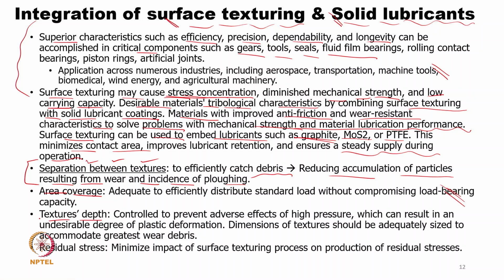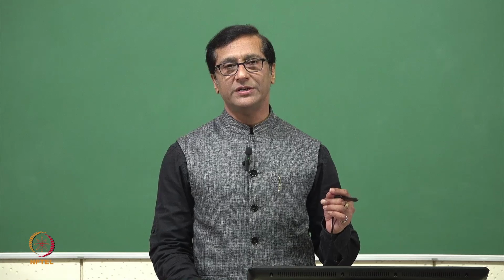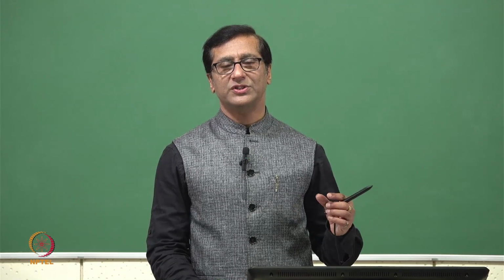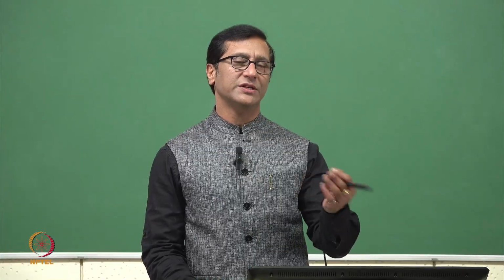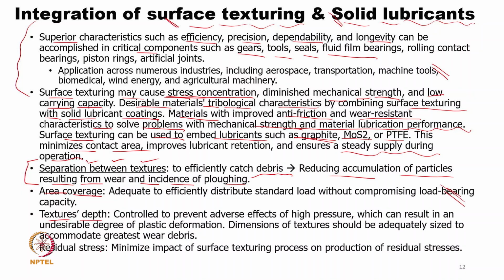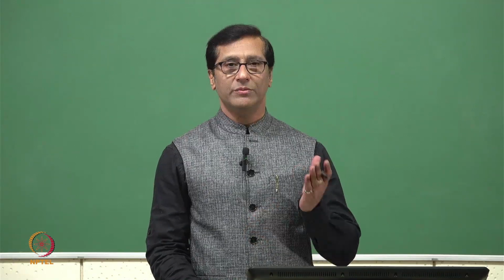Coming to the depth, often we say the shallow texture will be better, because in a deep case, once the lubricant is occupied, it will not come out, like a deep well. If there's a shallow well, naturally the lubricant will remain and can be utilized immediately whenever there are sliding conditions. So those conditions are important, and of course it should not have residual stresses. When we fill a lubricant in that, residual stresses will be lesser compared to without lubricant.